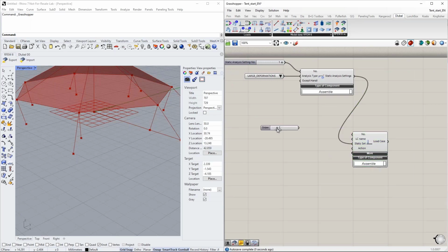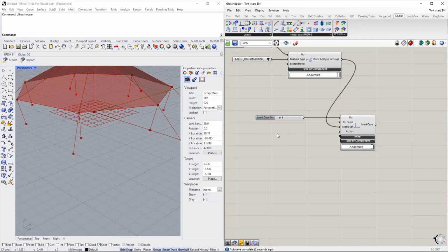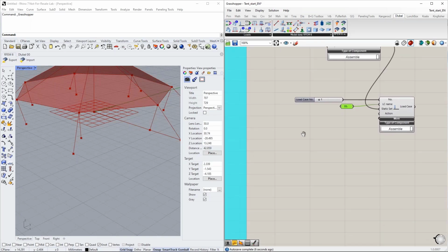Again, the load case gets an index number, so I can reuse it afterwards. For example, for load combinations. The name, well, we start with the dead loads. It's optional. Anyway, I assign it here. And then we only need the action category now. Well, as minimum requirement, the action category, yeah, is it a permanent load case, variable load case, in case it's like live load, different groups for Eurocode and so on. And you can assign the action category using this load case classification component.